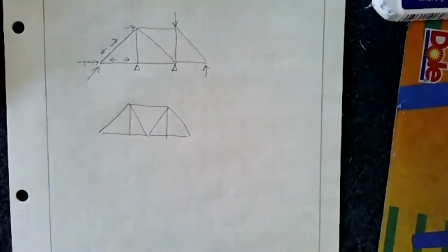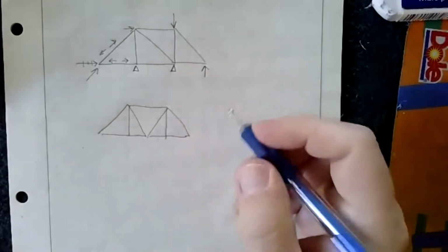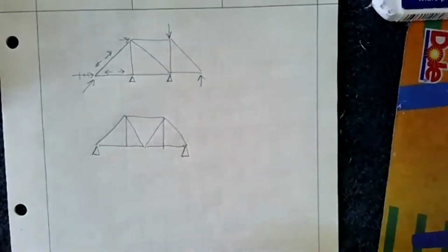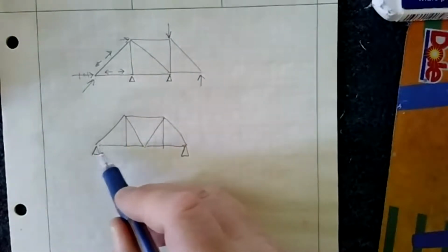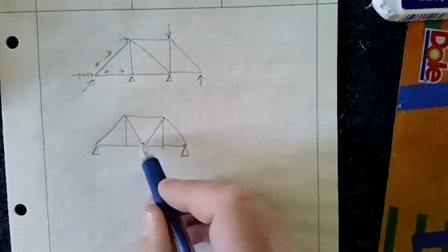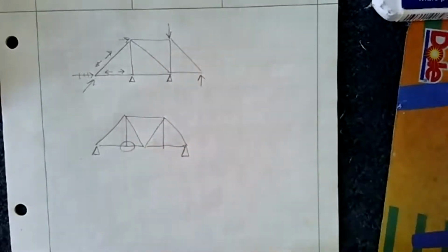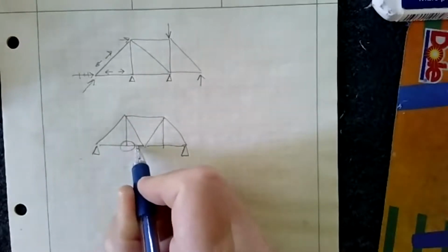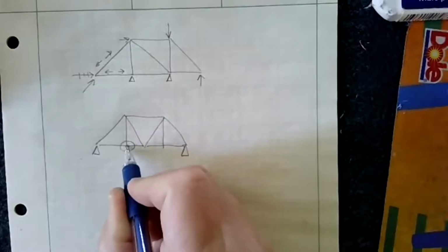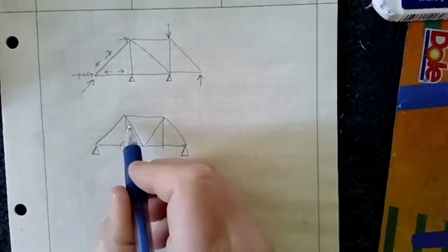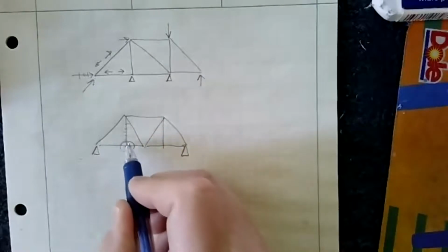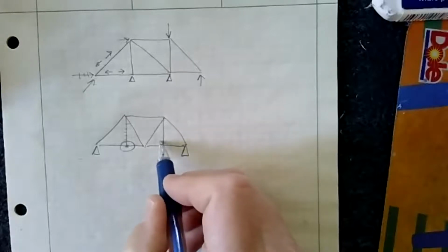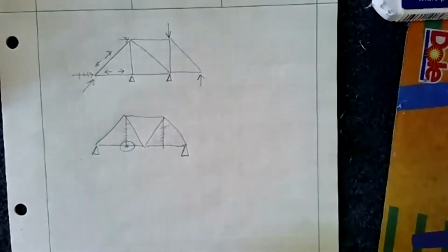There we go. So something like that, not very pretty, but if we support this truss here and here, then if we look at this, this is fine, it has an external reaction. But let's look at this here. If we have something like that, then we know that this is going to be opposed by this member, but this joint here has nothing to oppose this member. So in effect, this disappears. Same on this side, because there's nothing to oppose this direction. This will have to go to zero also.